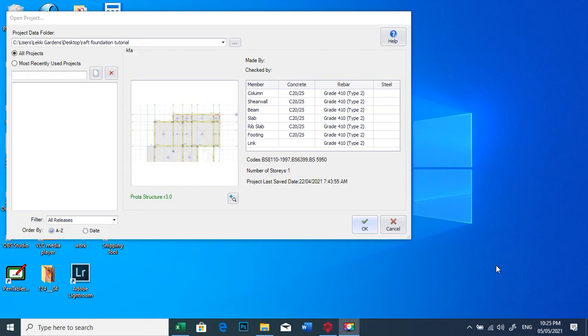Two things, that is it. Number one is if your soil capacity is not too good, and two, if you are designing high-rise buildings that have high column loads, then you will be advised to use Raft foundation for that design.